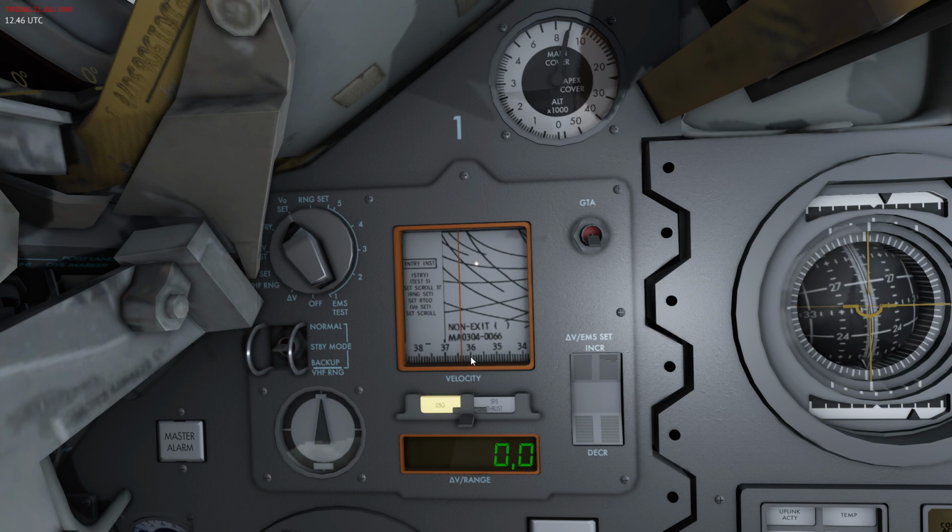That's 36,300 for lunar trajectory and around 25,500 for Earth entry. Keep it still in standby and then set it to entry. Once 0.5 G is detected, set this to normal. This is typically program 64, which is basically the upper part of the atmosphere.